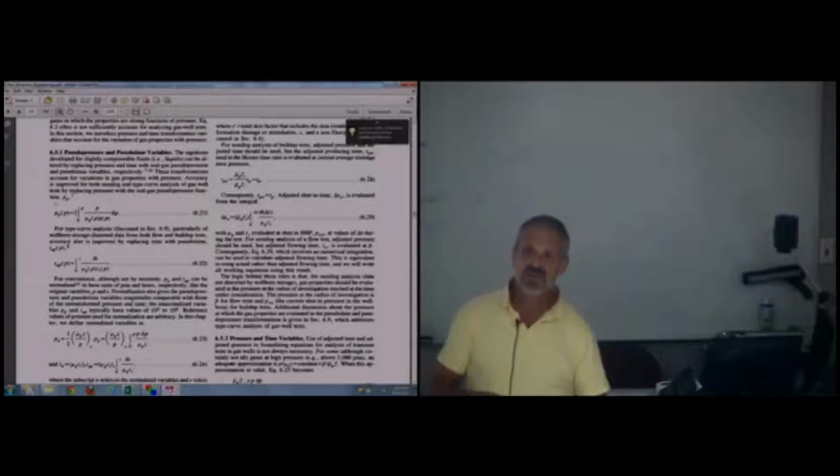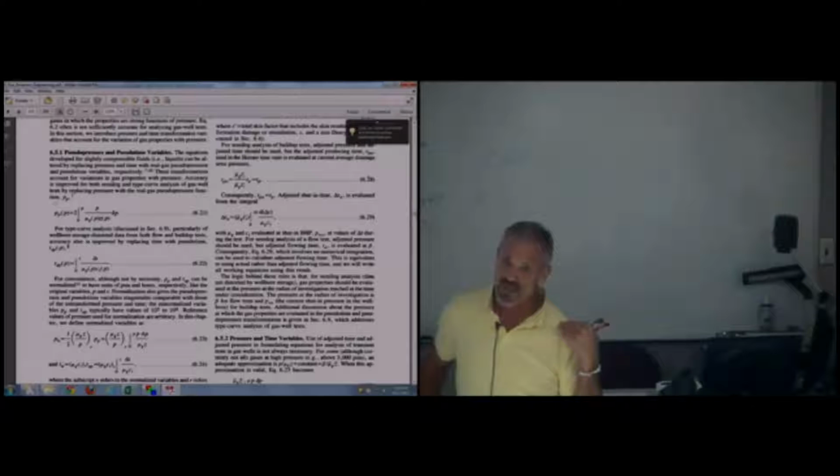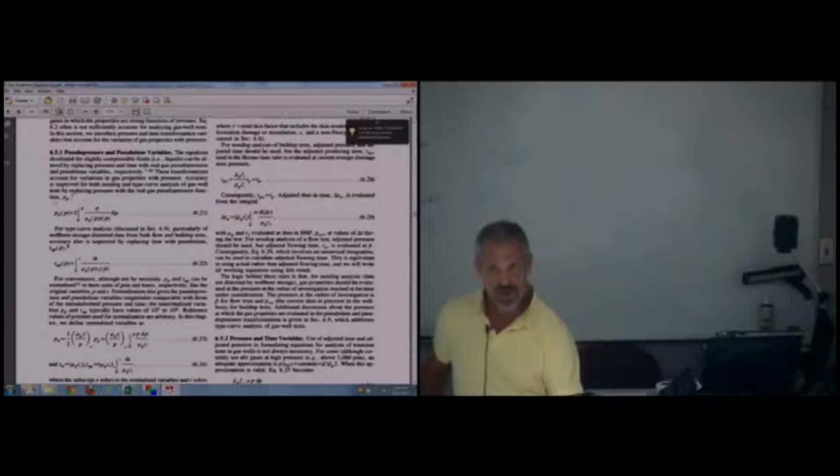And I pretty much stick with the viscosity that I get from this package that I got from what used to be on our calculators. You might remember the first class period. We used to have calculators that calculated all these correlations. And I think the textbook actually uses a different one. There are two very popular gas viscosity correlations, and the one my VB uses is slightly different than the one the textbook uses. And so I'm not going to always match the viscosity that's in some of the problems and some of the pseudopressures that use the viscosity. But we'll find that it only generates a small error.